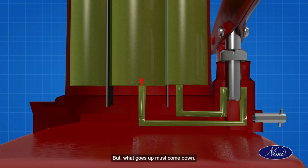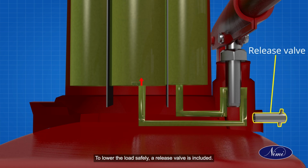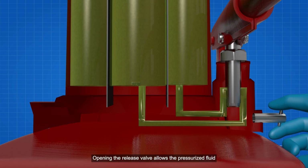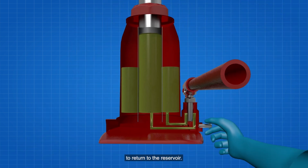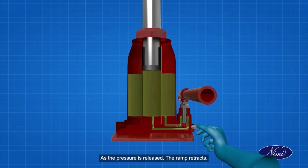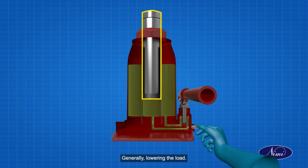But what goes up must come down. To lower the load safely, a release valve is included. Opening the release valve allows the pressurized fluid to return to the reservoir. As the pressure is released, the ram retracts, gradually lowering the load.